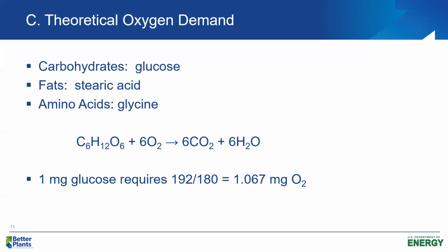And the city said, well, we'd like to take it, but we want to make sure we know the impact on our treatment plant. Well, what I was able to do was to actually calculate the theoretical oxygen demand, and I assumed it was 100 proof whiskey, which is 50% alcohol, and using the degradation of alcohol, I was able to estimate the BOD ultimate,